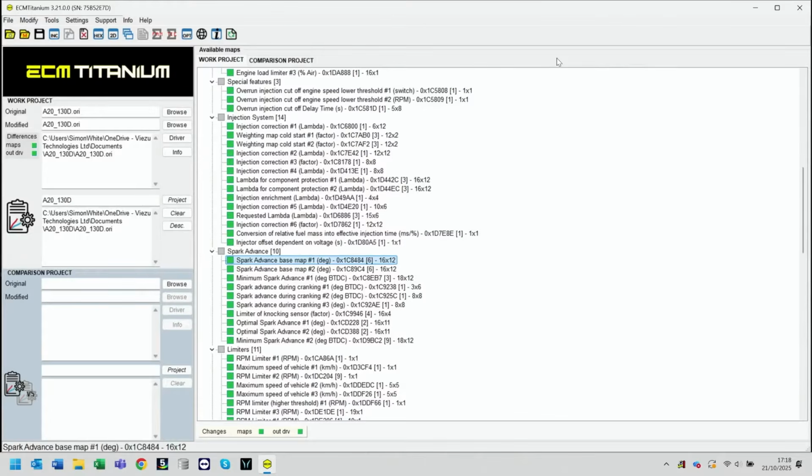Now, turbocharged engines have a lot more on the table than a naturally aspirated engine, of course, because with a turbo, we can force a larger volume of air into the engine. With a naturally aspirated engine, it's all about optimizing what you've already got. So the gains aren't necessarily always as large. Some vehicles are an exception to the rule, of course, but with those naturally aspirated engines, it's more about optimizing for a small improvement in horsepower and a better throttle response and mid-range. You won't basically see as big a gap between requests and limits and so on in the tables. But with gasoline turbo engines and our supercharged engines, we have more to work with.